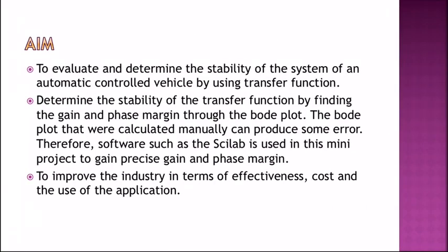Next is our aim: to evaluate and determine the stability of the system of an automatic control vehicle by using transfer function, and to determine the stability of the transfer function by finding the gain and phase margin through the Bode plot.